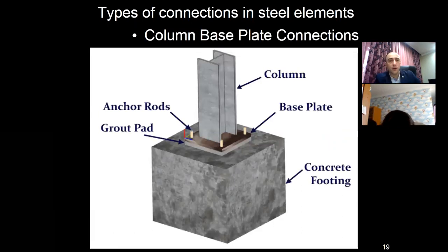Column base plate connection. This connection is used when we design column foundations with general steel columns. It transmits the vertical and also the lateral loads on the building frame to the soil through the concrete foundation.